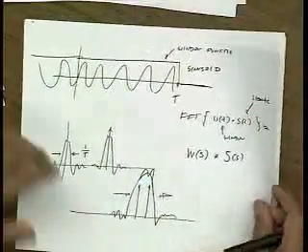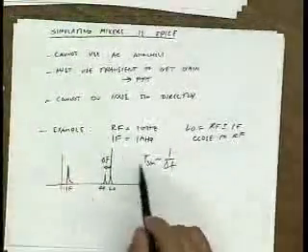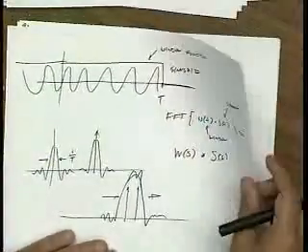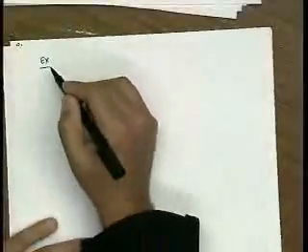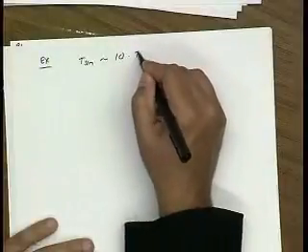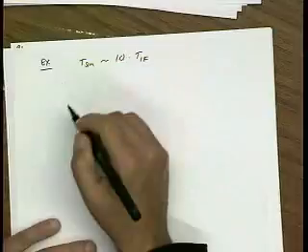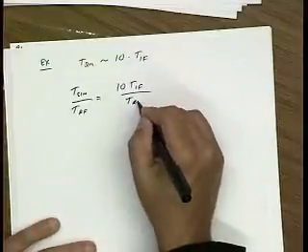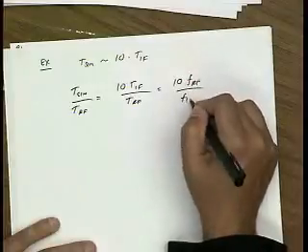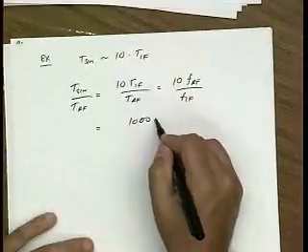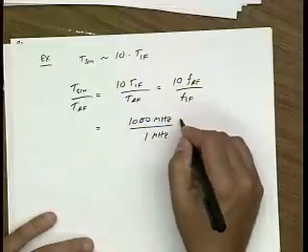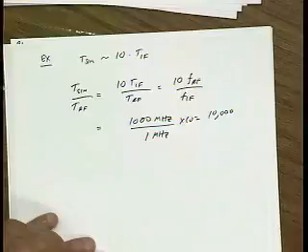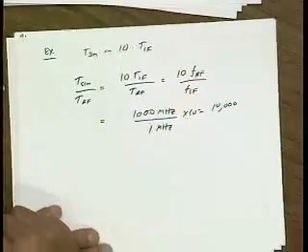So that means that coming back here to our example, we need to run, let's say, at least a simulation that's 10 IF cycles, right? So for our example, I want a t simulation time of roughly 10 times the period of the IF. Okay? And that means that if I look at the number of RF cycles within the simulation time, this is inversely related to the frequency of the RF divided by the frequency of the IF. In this case, the RF is at 1,000 megahertz, the IF is at 1 megahertz, and that's 10,000 cycles. Okay, so that's a lot of cycles.